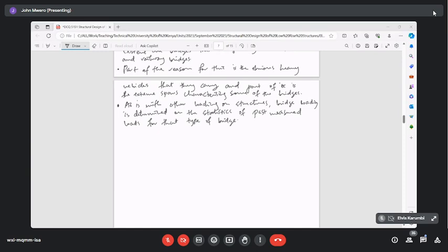Okay, so it's important to be aware that bridges are designed to loads that are historical. It's just like the way buildings are designed to earthquake loads that are historical, or to live loads that are historical. If we're designing a class, we say generally what has been experienced as loading for a class. Or if we're designing an auditorium, we say what loading has been experienced for an auditorium of this nature before. And then we use that loading. So it's the same thing with the bridges.